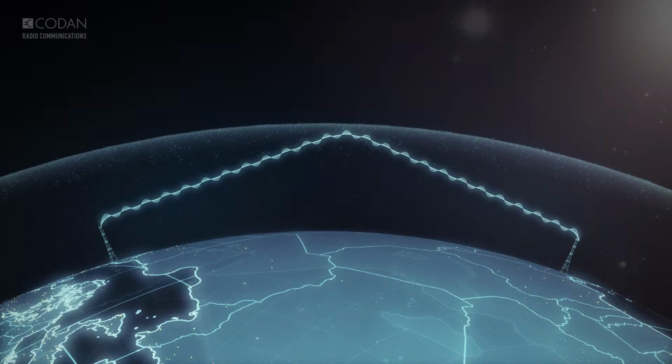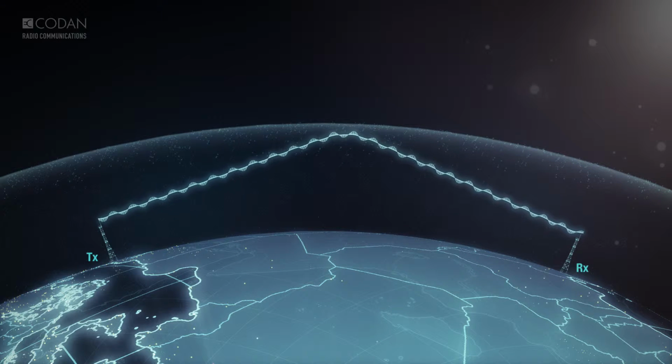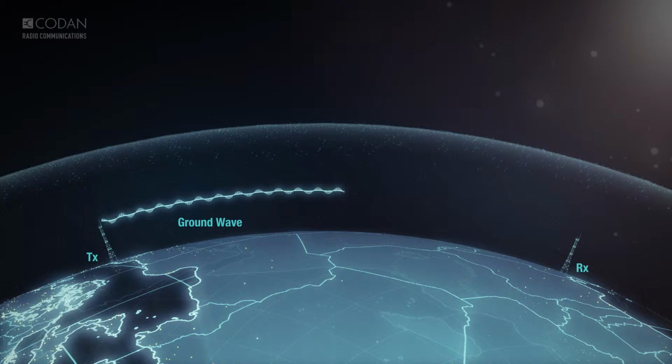How does HF radio technology work? A transmitting antenna, shown as TX, emits the HF radio waves, and a receiving antenna, shown as RX, receives these radio waves. There are three types of HF radio waves. Ground wave, which is good for short-distance communication at less than 20 kilometers. It follows the curvature of the Earth and is therefore attenuated.